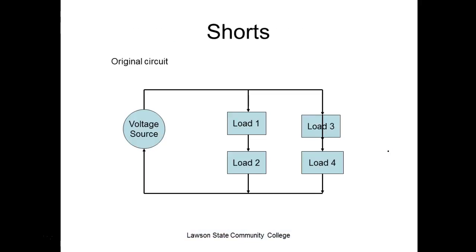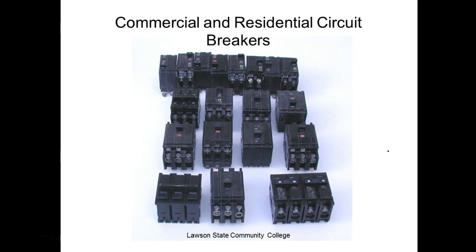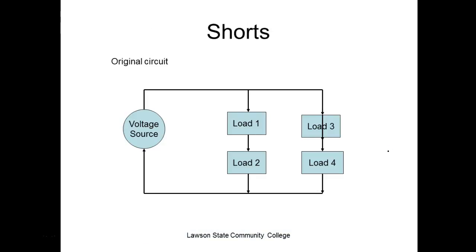So you go out to US Steel or someplace like that, you're going to almost see no circuit breakers because they use a ton of fuses. The fuses that they use normally have a replaceable fuse link inside. We don't have that over here. If it was over motor controls, I could show y'all. But what happens is your two end caps on your fuse twist off, and you replace the link. So you don't replace the unit or tube that it's in, which saves a pretty good deal of money.